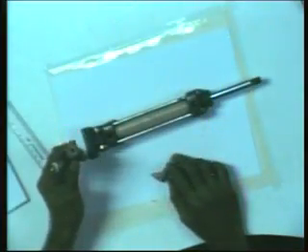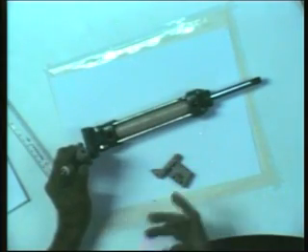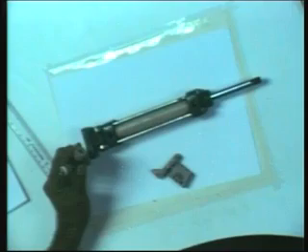One of the disadvantages of pneumatics and hydraulics is energy exchange. An electric motor drives a compressor, so there is a loss of energy there. Then the compressor compresses the air, there is some more loss of energy. The air is again in turn expanded in the cylinder to push, there is a loss of energy, there is friction. So you are paying a lot just for that movement. In the case of hydraulics, you need a huge hydraulic power pack where the oil is pumped through the valves and all. You have to generate the pressure and pump the oil.